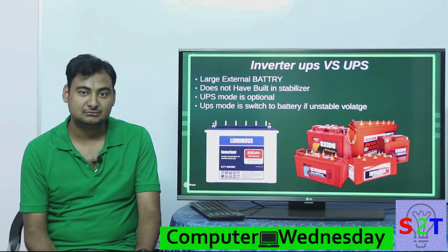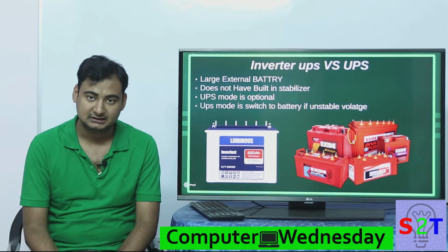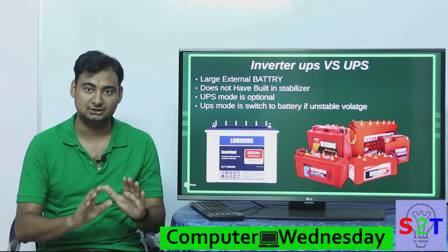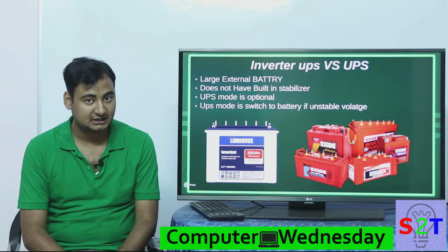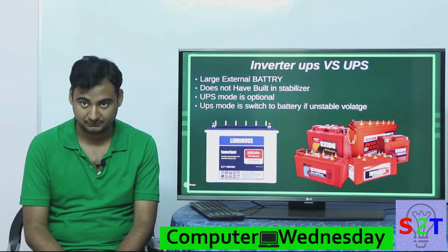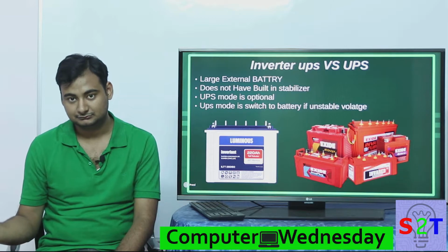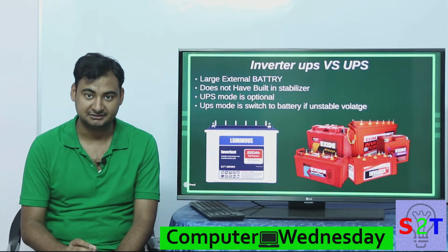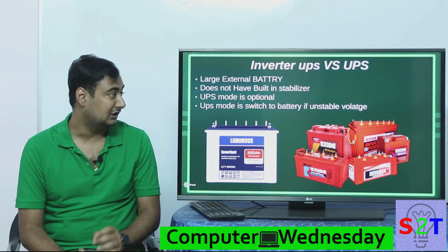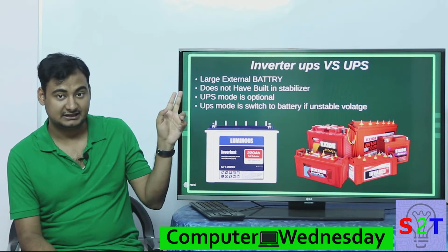Many of you have recently noticed a trend that all the inverters are also saying UPS come inverter. What they actually are is very simple. They are only giving you a switch of UPS grade. Basically, they switch from battery power supply to your main line power supply in less than 5 milliseconds. That's the whole point.